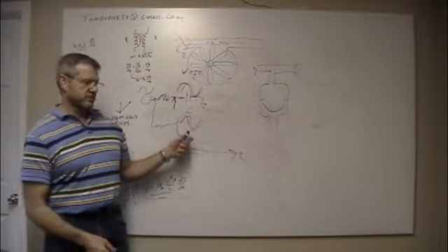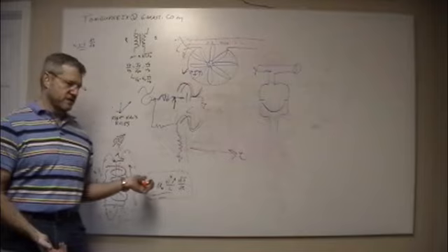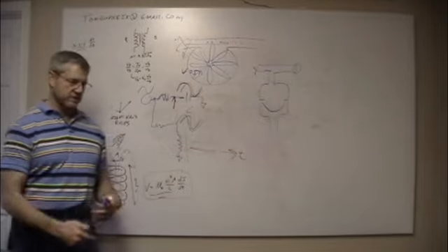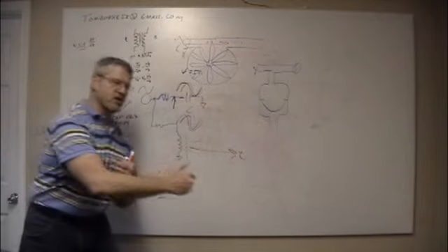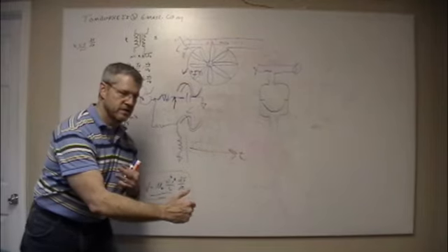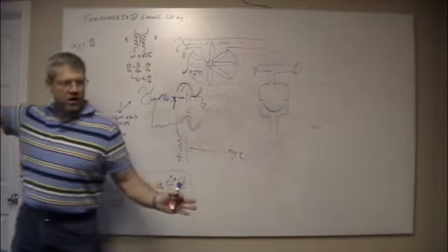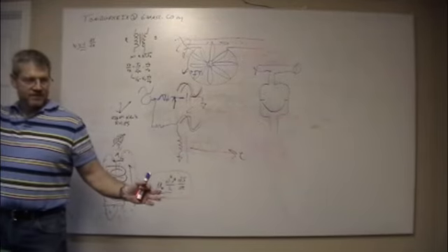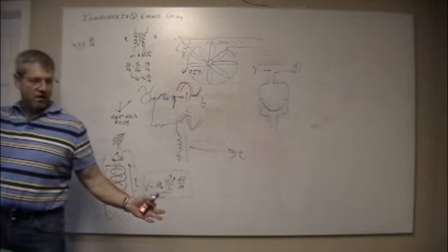When it hits an electric motor, okay, a DC electric motor doesn't matter, but now you get into an AC electric motor, and now you start having these things happen. Then you're pulling current ahead of the voltage, and that's overworking the generator back here. It's actually as if you're pulling more current than you really are.